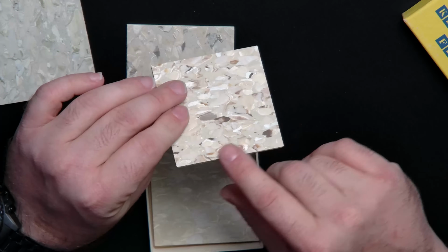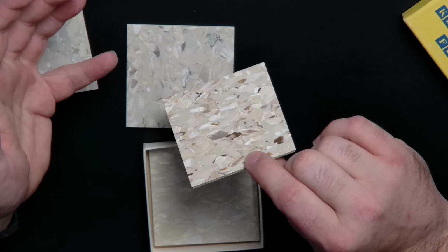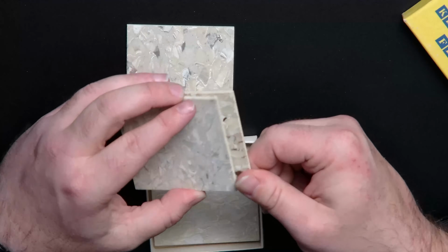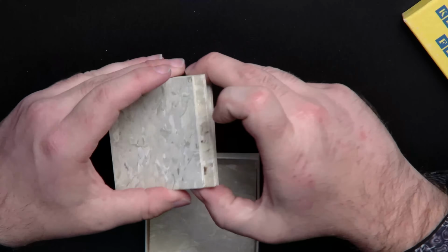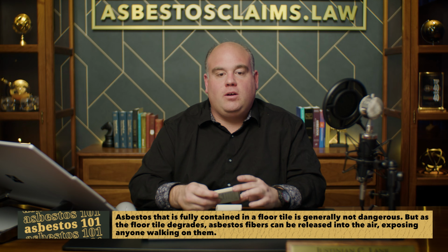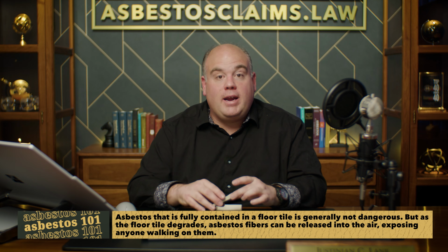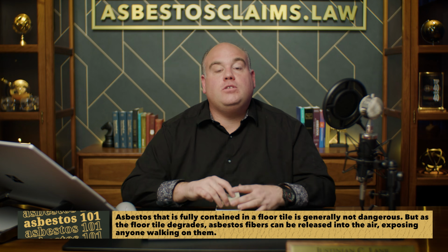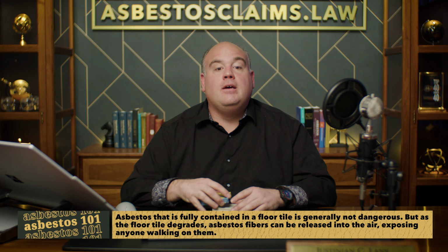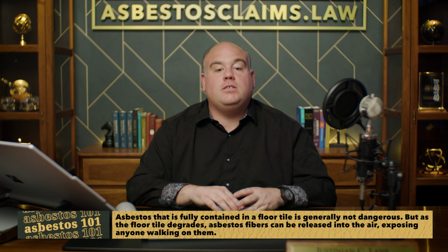And because this is what the industry called locked in or encapsulated, the asbestos isn't going to go anywhere from this unless I start sanding on it or filing it or grinding it. So I have no worries about this stuff at all. So the lesson to you as a homeowner, if you're going to do a home improvement, is if you have floor tile like this and think it's ugly and want to get rid of it, that's great. But make sure proper precautions are taken with an asbestos abatement company so you don't end up putting asbestos all over your house when you scrape it up. So that's what asbestos floor tile would look like.